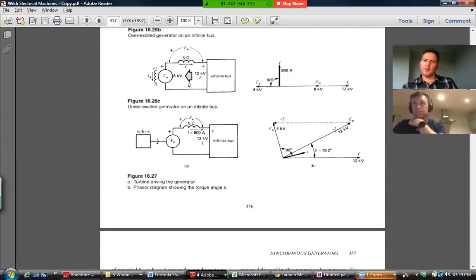And the vector diagram will look very similar, but this thing here will be sitting down here somewhere underneath the line, and the EX will also turn around. But again, the more we resist this thing with the load, the wider that angle will actually get. I'll go to the diagram for it in a minute. The wider that angle will get, and the more real power we would need, the bigger that EX vector, the bigger the current, etc., making you need more real power to achieve it.